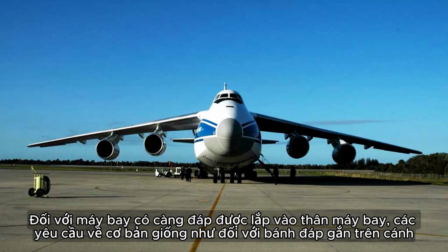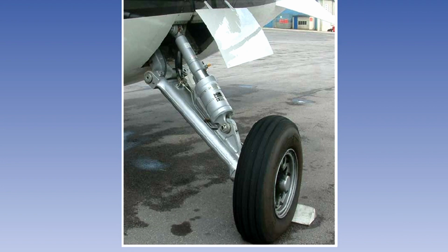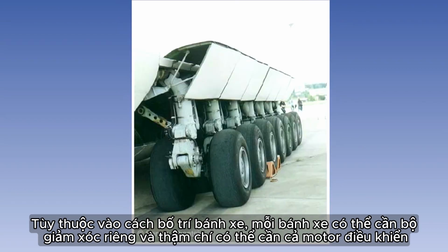For aircraft with the landing gear built into the fuselage, the requirements are basically the same as those for wing-mounted landing gear, except that often the gear mechanism may not be long enough for geometric lock to be available, so an alternative provision has to be made for locking the gear both up and down. Depending on wheel layout, each wheel may require its own shock absorber unit, and possibly even a steering motor.